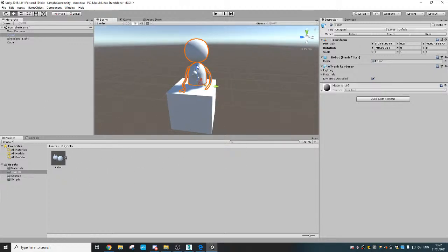If you did not do it properly, then what will happen is your sizes will be 100 times this. It will blow up to 100 times the scale. So you'd have to put it to 0.1, 0.1, 0.1. But instead of changing it, it's best to get the scales correct from 3ds Max, and that's why we put on the XForm to reset everything.